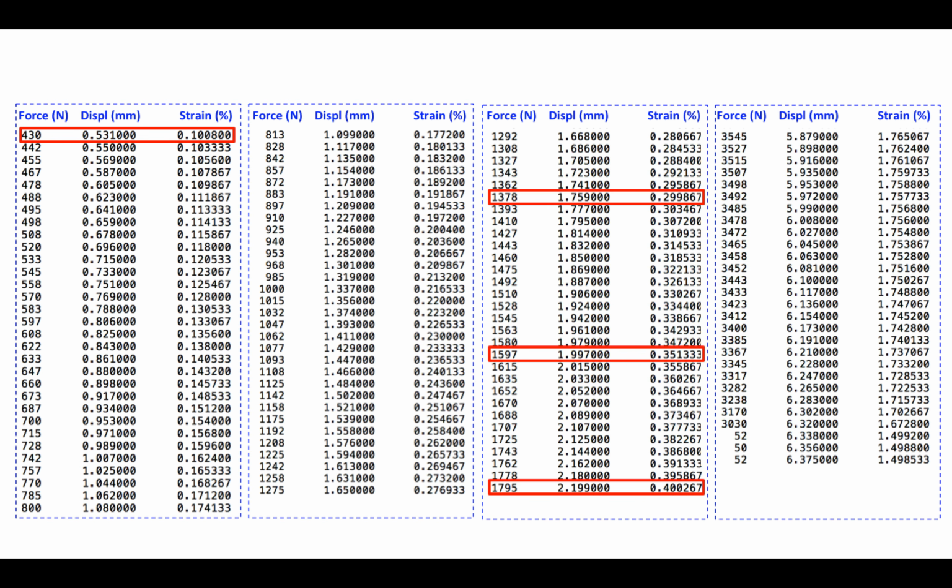This fourth column picks things up several minutes later when our force has gotten all the way up to 35-45 newtons with a 1.76% strain. At this point, the metal in the spoke has gone way beyond the yield point, obviously, and it can't even stretch any farther without totally disintegrating.